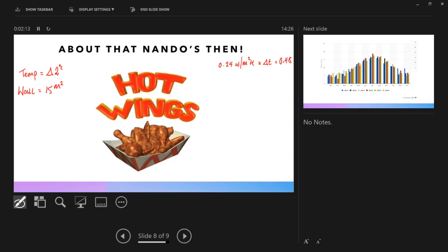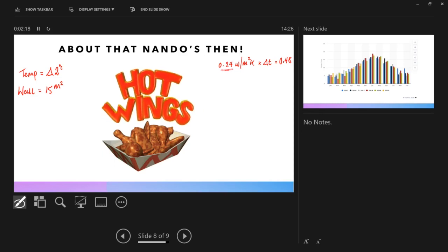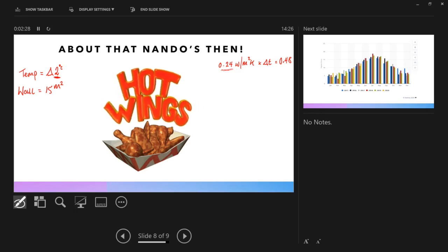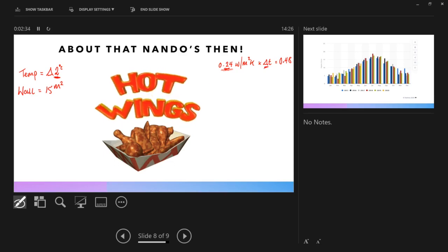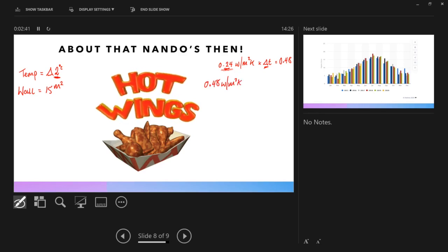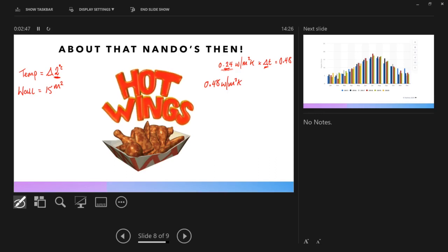Hope you follow me so far. The 0.24 was taken from the previous worked example we just did. So for every square meter, it's 0.24 times delta T, which is the difference in temperature. There's a 2 degree difference. That's what we got here. So it's 0.24 times delta T, which equals 0.48 watts per meter squared Kelvin. We don't have to add the per degree difference because we factored that in with the delta T. It was 2 degrees. So what does that equal then?